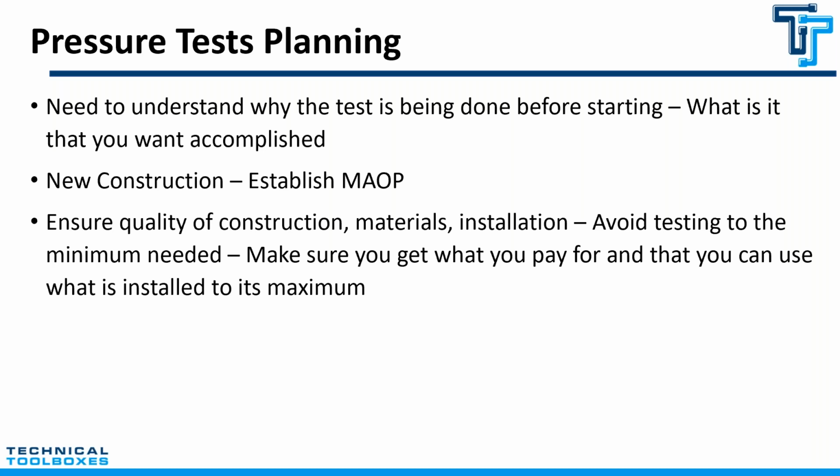So how can you do this process and make sure that regulatory handouts are done and you are in compliance? One of the things is looking at the pressure test planning. You need to understand the reason why a pressure test is being conducted and what you want to accomplish. Is it a stress test for the pipe, or a revalidation for the pipe based on a location class change? All those things play a key role in helping you design an effective hydro test plan that can then be communicated to your contractor or to the engineers who are executing this.